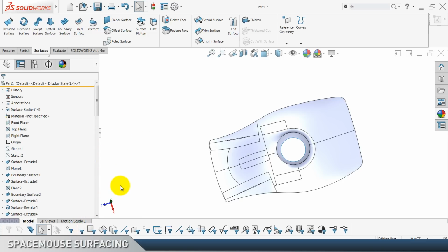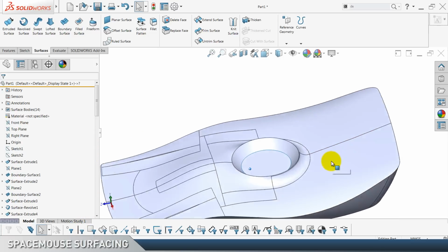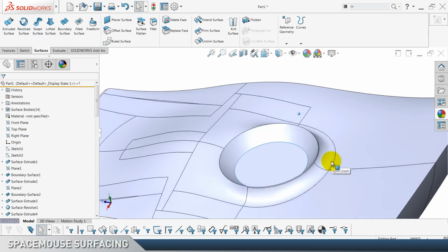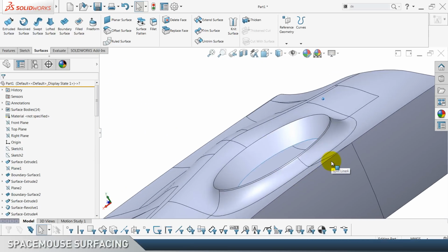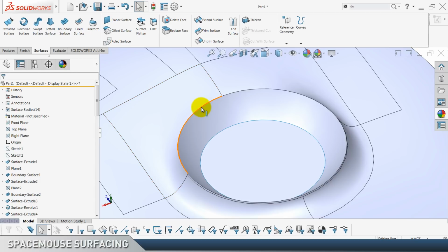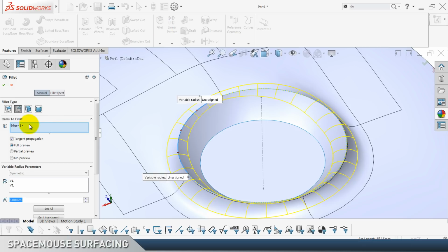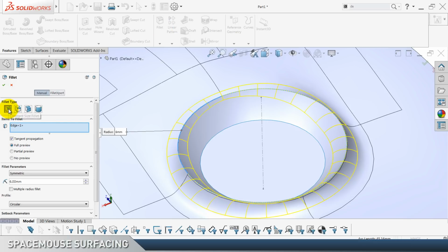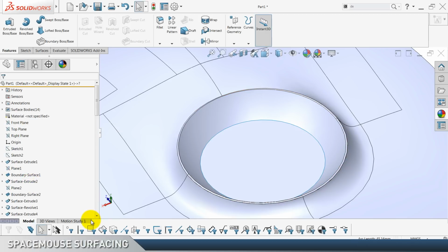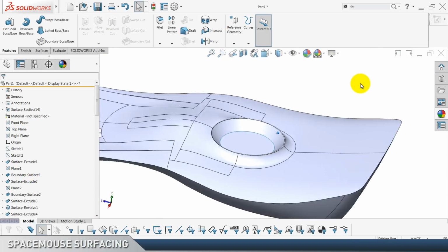Deselect filter edge, and the only thing left is one fillet. Here is gonna be for this edge. Now if this doesn't work, I'm gonna shoot myself in the leg. So just a normal fillet of 0.35, and it worked. That's nice.